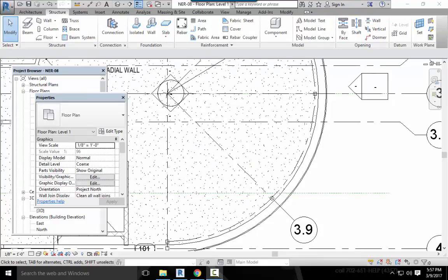All right. Now you'll place columns in the main part of the wing. Place a column at every grid location. Note that you must stretch the column lines to the left side of the wing. You should also turn on grid bubbles at the west and south sides of the building, as shown in figure 8.28.